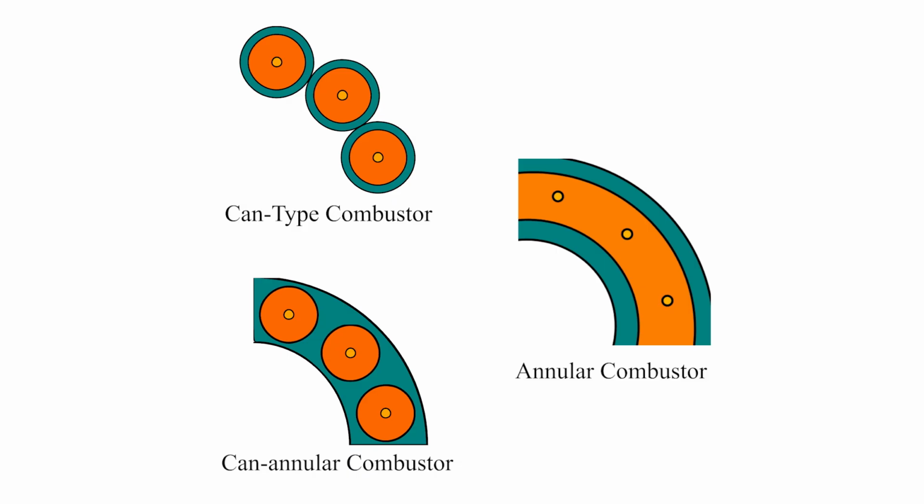Next, let us learn about ramjets. Ramjet engines differ in many ways from traditional gas turbine engines, but most of the same principles hold. One major difference is the lack of rotating machinery after the combustor. The combustor exhaust is directly fed to a nozzle. This allows ramjet combustors to burn at a higher temperature.